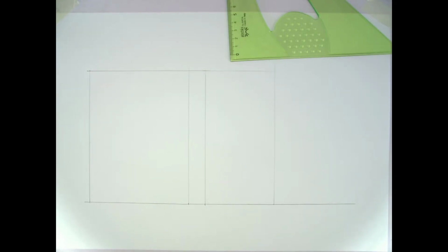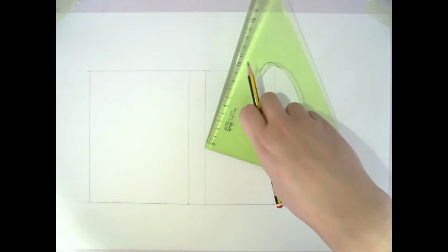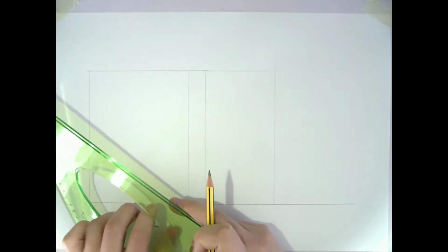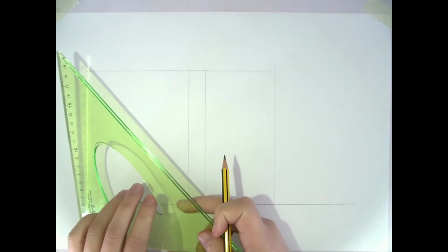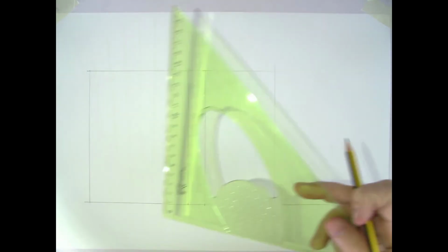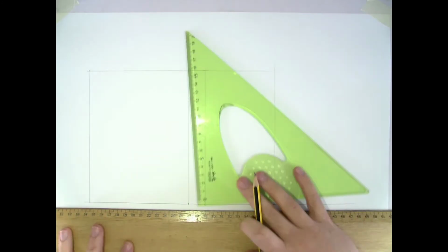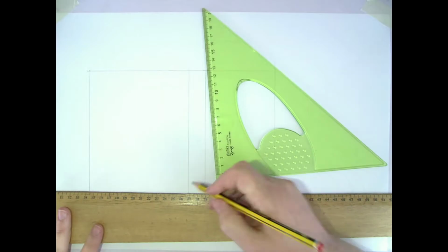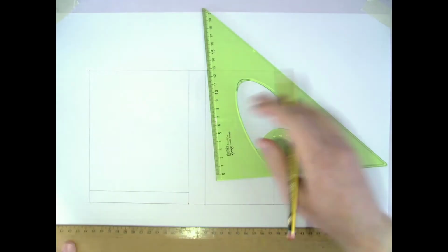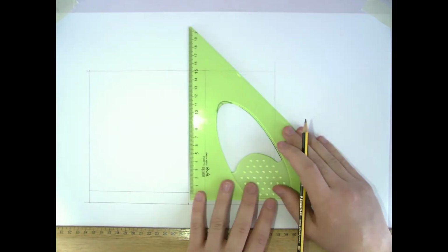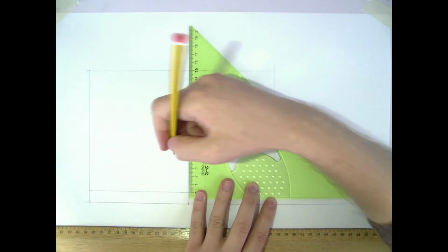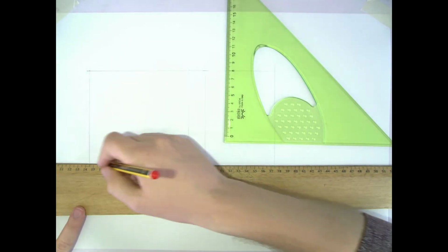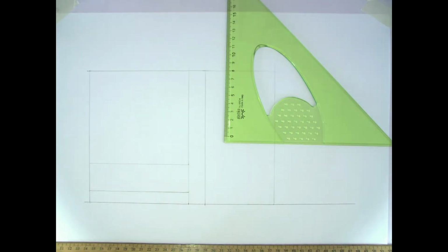So we're going to start by drawing the elevation first, or part of it first anyway. I'm going to start with the block part, with the dark grey bit of it in the question. So that has a total height of, it's up 15 first for the lower part. So we can mark that bit, that's the line across the front. And then it comes up a further 35 for the very top of it. So we can draw that in lightly just for the time being. So put all your lines in lightly to start off with, as we don't know how different pieces are going to interact with it.